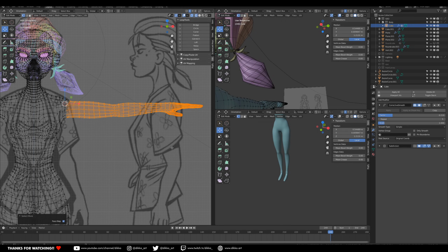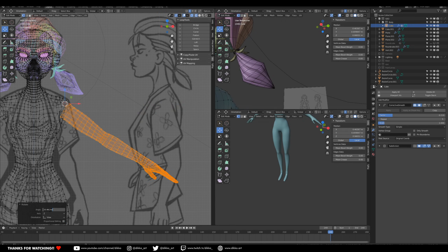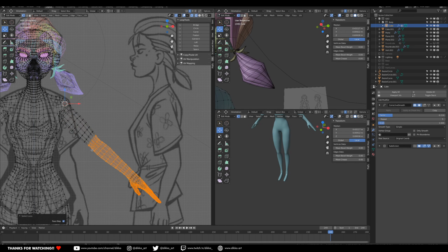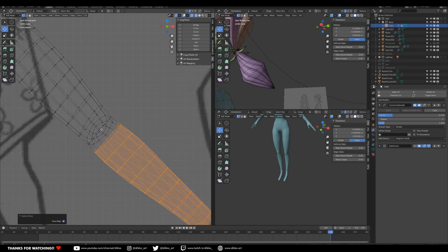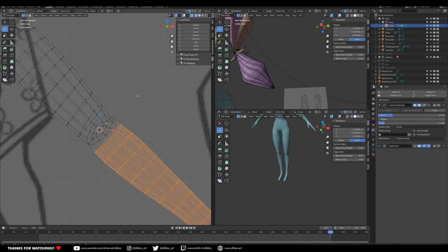So as you can see, I've placed the 3D cursor at the point of the shoulder, and using soft select, I've rotated the arm exactly 45 degrees. And I'm going to repeat that process at the elbow. So reducing my selection using Control-minus on the keyboard, I'm going to place the 3D cursor at the elbow. But here's a handy little trick. Using the 3D cursor's rotational feature now in Blender 2.8, I'm going to use the 3D cursor's rotational orientation to help aid in the rotation of the forearm.